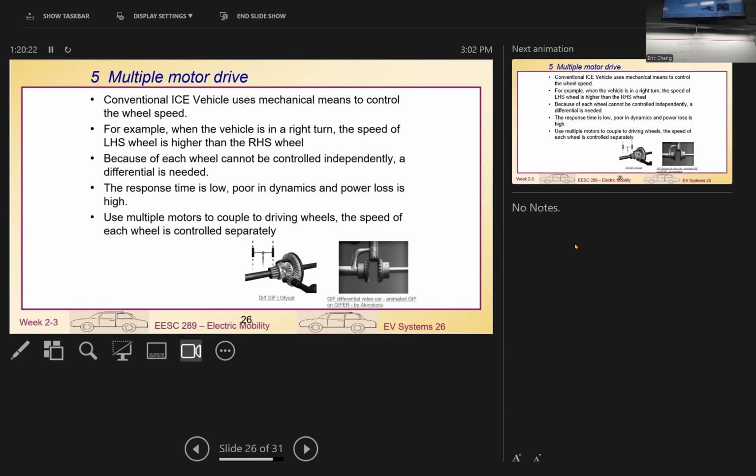And also each of the wheels we need to control individually for the ABS. That will be really difficult for a mechanical car or for a hydraulic control system. Then when you use electronic brake, I can control each of the motors individually. Each of the motors, we can control brake individually. So in this case, I am able to achieve ABS for each of the wheels independently.